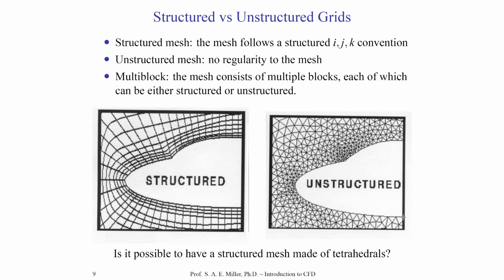For example, this might be connectivity 1 to 2, and then this particular node might be connectivity 2 to 43, and 43 to 54, and 54 to 26, etc. Out here, we might have node 17, and this might be node 48, 17 to 48. The whole list of connectivity simply describes the connection between the nodes. Now, typically, the mesh generation software, which we'll talk about in a few classes, and their algorithms, does have some kind of logical order for the way the nodes are constructed, but it's very difficult in complicated three-dimensional meshes to understand. This is why the list of connectivity is so important.